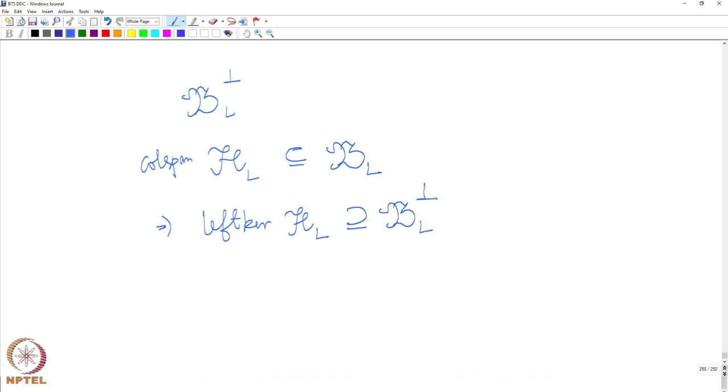So, that means I will have equations, right, but I do not have exact information about BL perp. I have something which is bigger than BL perp. So, I have information about a smaller behavior, because I am having a bigger module. So, I do not identify B per se, but I identify a behavior which is smaller than that, which explains the finite time series data.